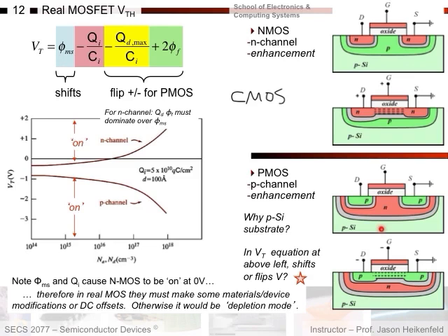Well, think about that. If I need to have complementary metal oxide semiconductor circuitry, I need to have both the NMOS and the PMOS on the same substrate. And so you could see I set the doping level here to be ideal for NMOS. So it's set to a P level doping that's ideal for NMOS. And then here I diffuse in phosphorus atoms to create my N-type area, which I can then invert to my P-type channel. So this allows me to integrate both of them on the same substrate.